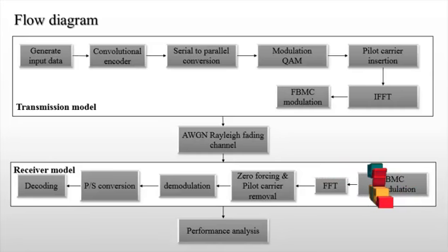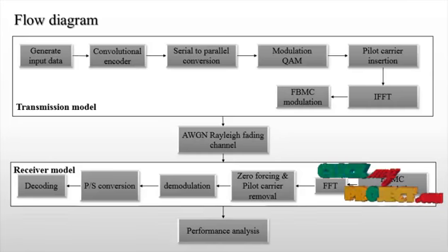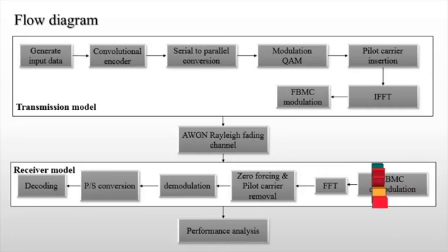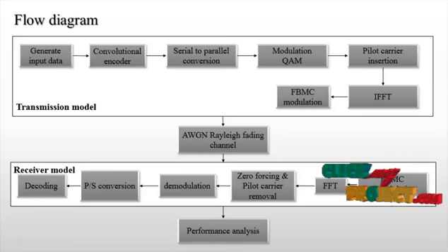The Fourier transform breaks the signal into different frequency bands by multiplying the signal with a series of sinusoids. This essentially translates the signal from the time domain to the frequency domain. And then the filter bank. The filter bank concept is an array of bandpass filters that separates the input signal into multiple components, each one carrying a single frequency subband of the original signal.